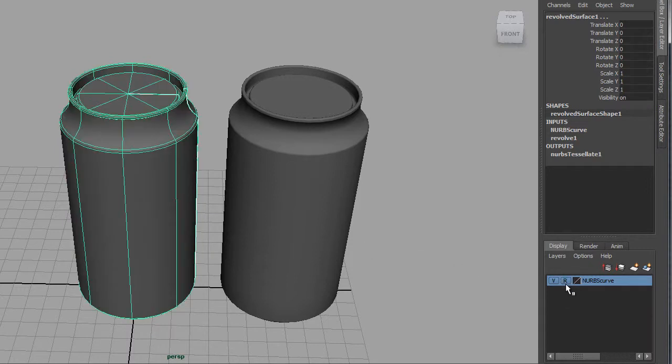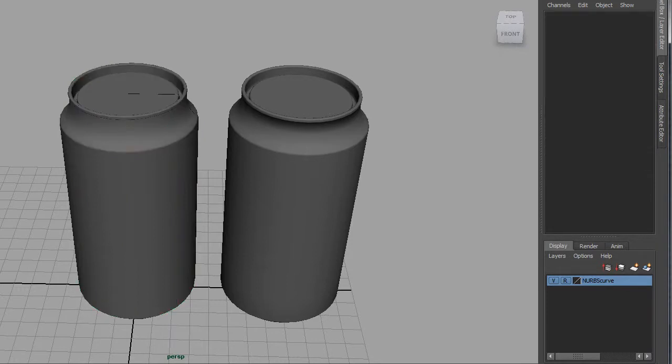All right, I'm going to click it again. So I click the T, and it switches to an R. Now this is a reference layer. So once again, the layer's locked, and I can't do anything to the objects in the layer now. You can see it's still selected. If I deselect by clicking in an empty spot on the grid, and then I drag across again to try and select those objects, they won't select. So that layer is now locked.